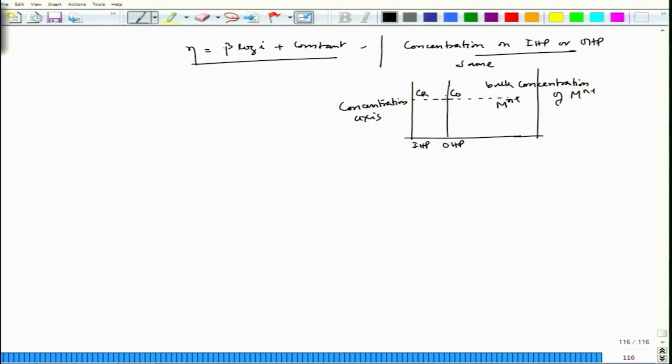Now, if I try to see this particular reaction, which is a cathodic reaction, if we have this continuous cathodic reaction, there could be a possibility that metal ion is consumed heavily, so that there could be a depletion of metal ion at the interface with regard to the bulk concentration of metal ion in the aqueous solution. So, we have a concentration difference. That concentration difference might lead to some polarization again. That polarization is called concentration polarization. We will talk about that part.